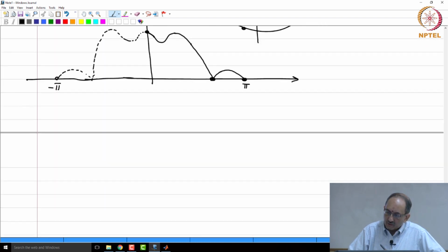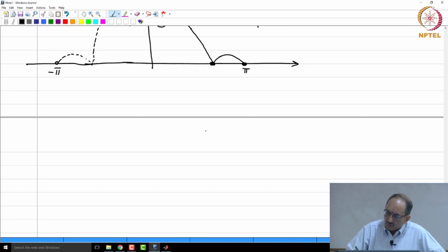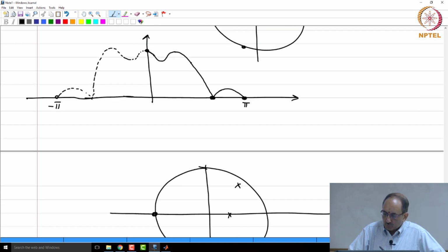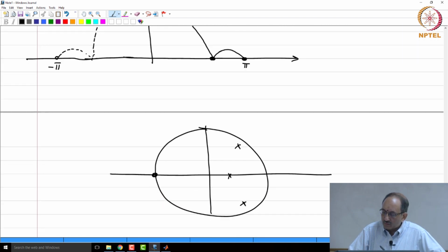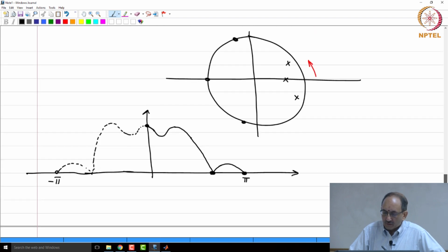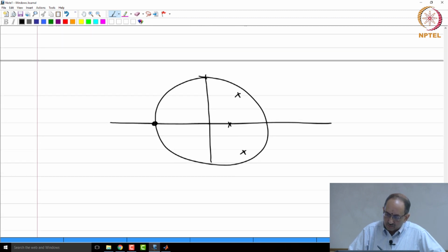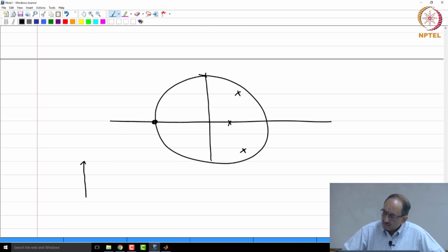There is another kind of filter which is called the Butterworth. Let me draw the pole-zero plot of a third order Butterworth filter. The point to note here is these poles, if you look at this plot compared to this, are clearly further inside. And it so happens that if you plot the frequency response of this filter, the response will be something like this.